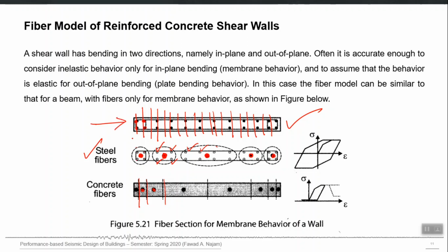So this shear wall is designed to resist only in plane loading, which means that if you're looking from the top, and this is, let's say, the seismic load V in this particular direction, you can imagine how this leg will bend. So the side view will look like this, right? Now let me draw a bit of the cross section also like this. Now you slice this, so these are all the fibers, right, like this. So this is how the shear wall leg will be sliced, right?